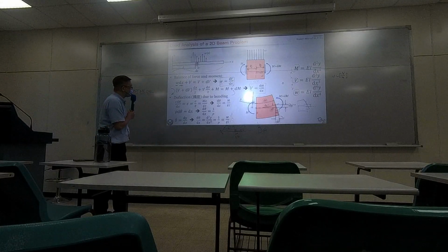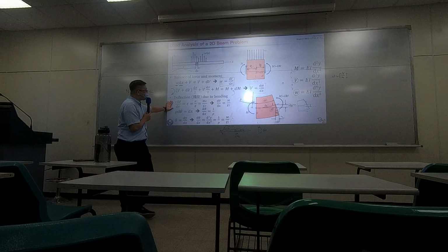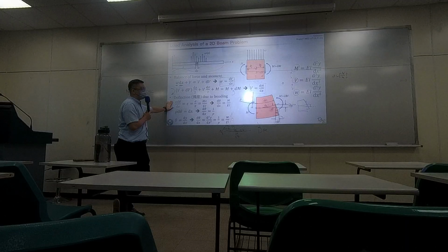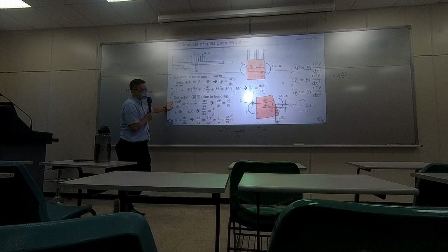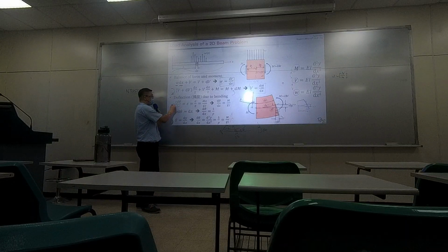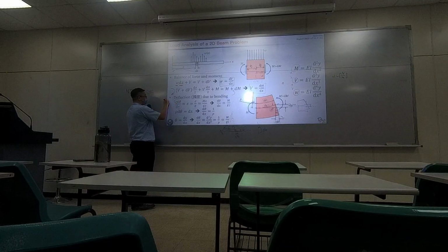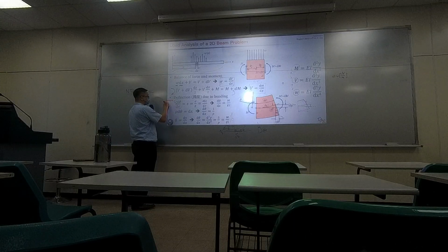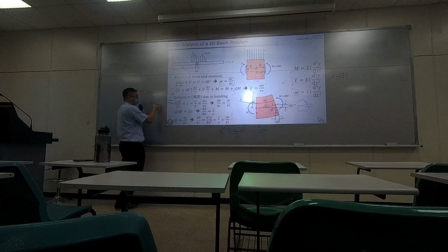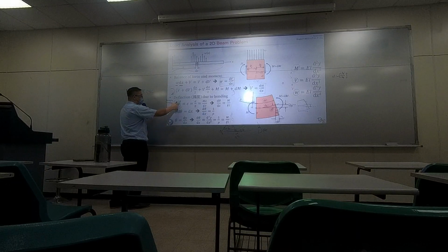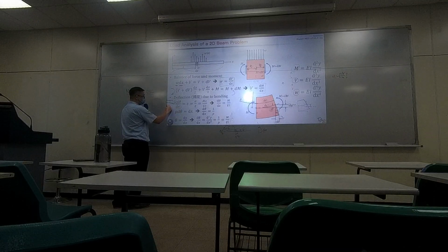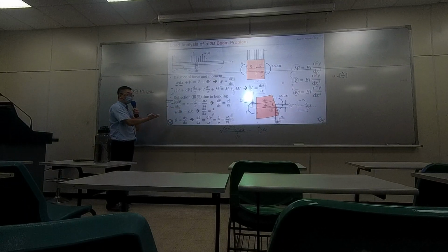Now let's take a look. What is C d theta? C d theta is the increment in length. Originally the length is dx. And this is the length increment. So basically, deformation in x. So if you have deformation over original, this is the original length. What is the definition for that? It's strain.